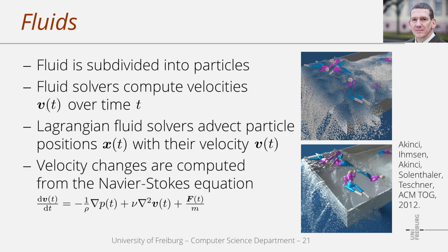The second acceleration term accounts for viscous forces. Nu is a parameter that describes the viscosity of a material, and the respective force tries to accelerate a particle such that the difference between the particle velocity and the average velocity of all surrounding particles gets minimized. This can be interpreted as friction in case of adjacent particles that move with different velocities.